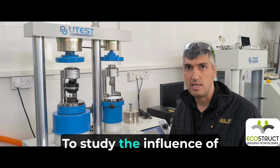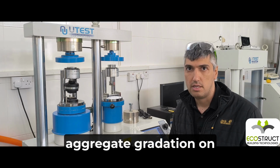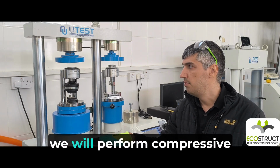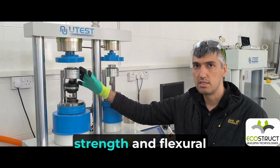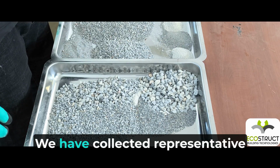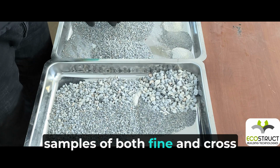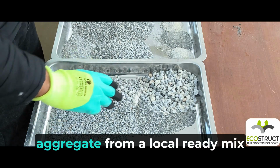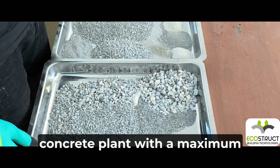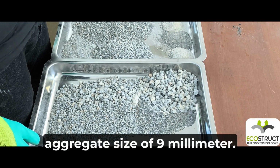To study the influence of aggregate gradation on concrete strengths, using this machine, we will perform compressive strength and flexural strength tests. We have collected representative samples of both fine and coarse aggregate from a local ready-mix concrete plant with a maximum aggregate size of 9 mm.